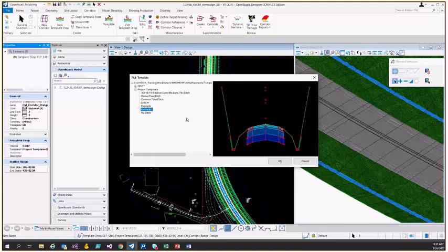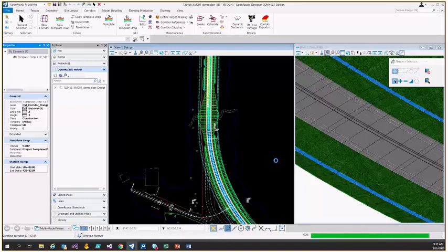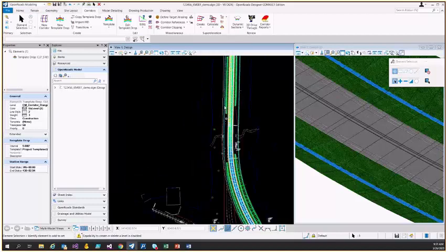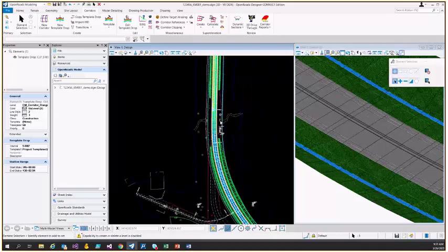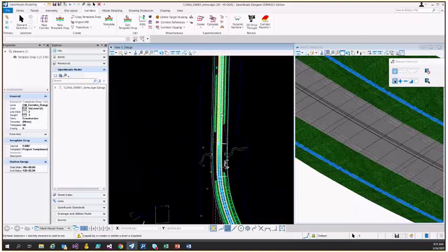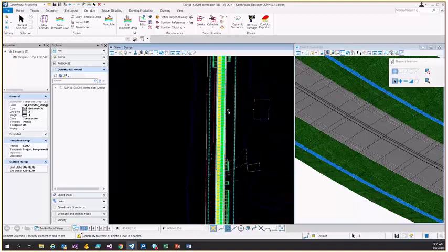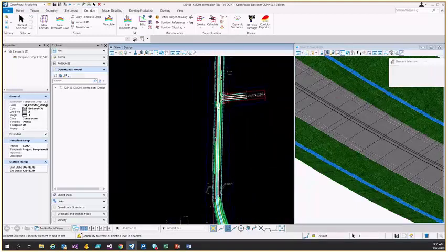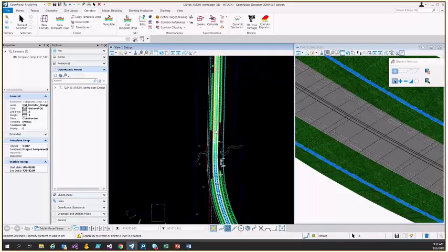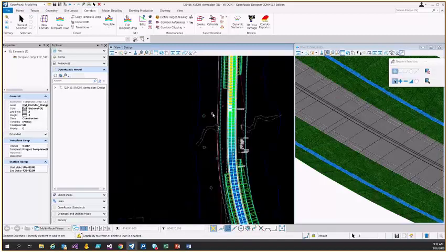So I'm going to first push through with a non-fixed ditch. What happens? You'll probably see a whole bunch of gaps because it couldn't solve. So you see right here, it didn't solve. I think I remember as we come into this, we're increasing the elevation. But there's all these areas where it didn't solve, which, maybe in those areas we don't need a ditch. So depending on the situation, in some of these cases you do want to force a ditch through here. And especially right here, you're probably going to push this out for your culvert here.